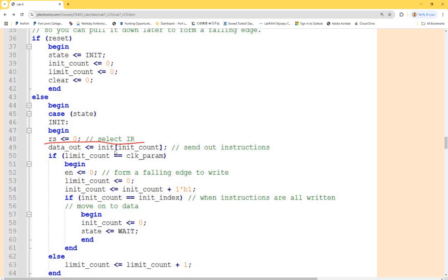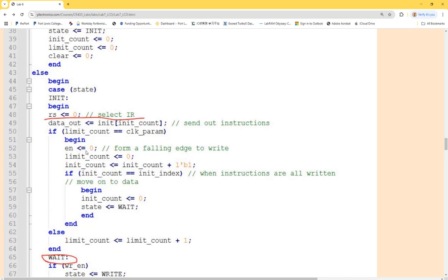The minimum is a few hundred nanoseconds, but it's always delaying just 1 millisecond, way longer than the minimum, so there won't be any timing issues. But if you want to run it faster, you probably want to reach that minimum time limit. For now we're just using 1 millisecond, giving it enough time to do the time delay and setup. So do a 1 millisecond time delay and eventually give a 0 to it.